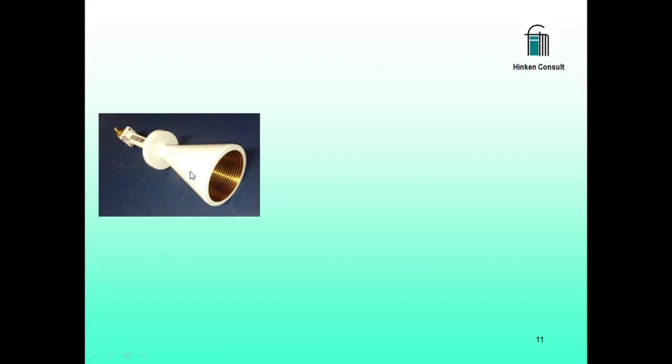Now we have to ensure parallel rays at the input of the lens. That could be done with a small radiator, like an open waveguide, rather far away. But that would cause unnecessary losses. Best is to use a closed wave transformer. A so-called corrugated cylindrical horn can do this. It produces parallel rays which are distributed homogeneously over the aperture.